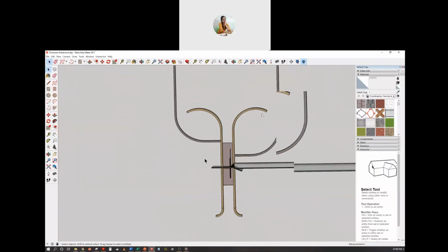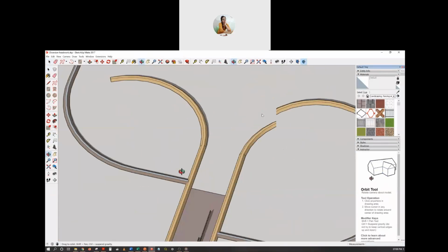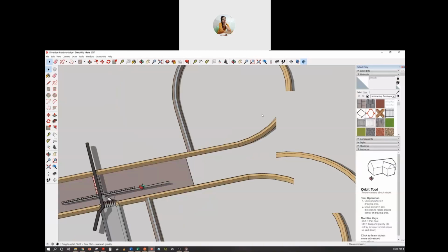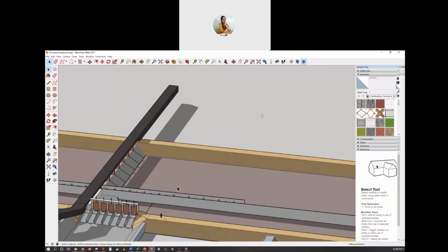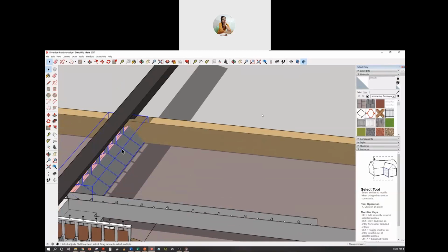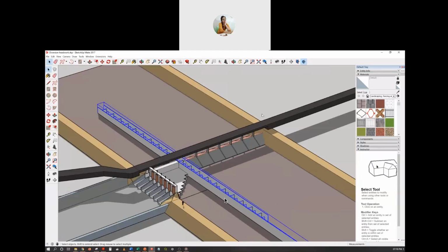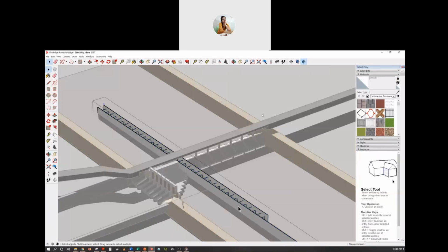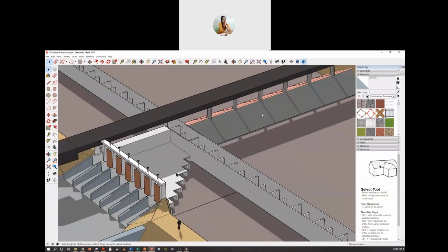So water comes in from this direction, and here it is stored and the level is raised because of this weir, and this divide wall makes sure that in this portion the water is not having lots of secondary currents or eddies. Now,